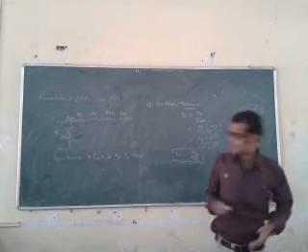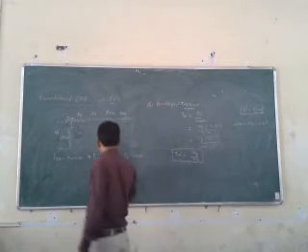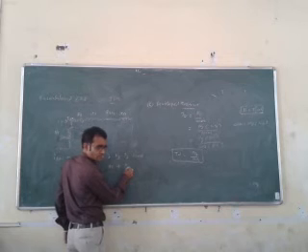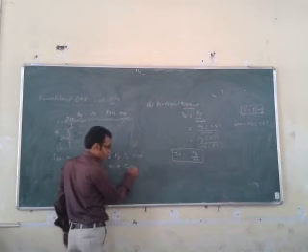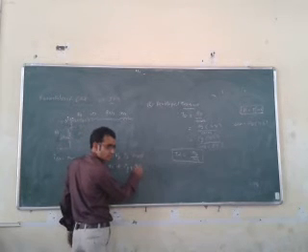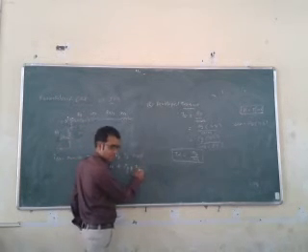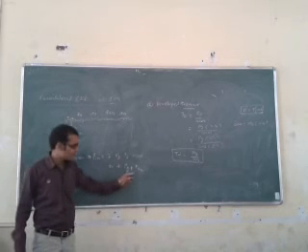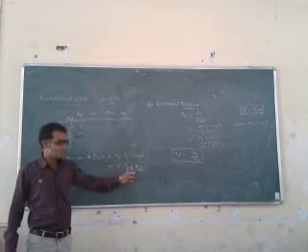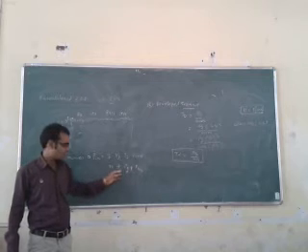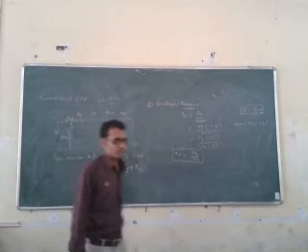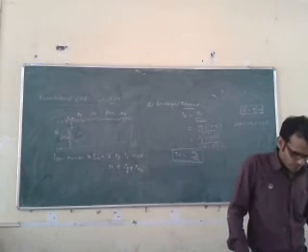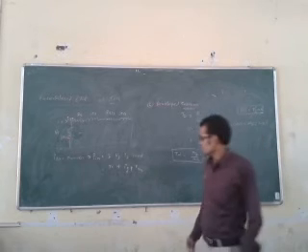So it is equal to PC plus PS plus PG. Power inside: the stator loss, the core loss, and then the gap power, which is the power transferred from stator to rotor.